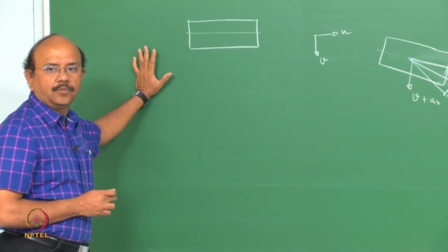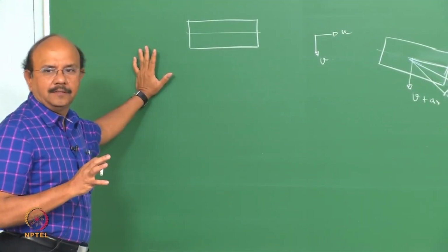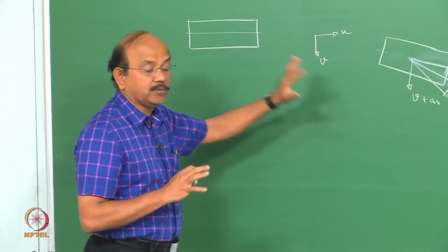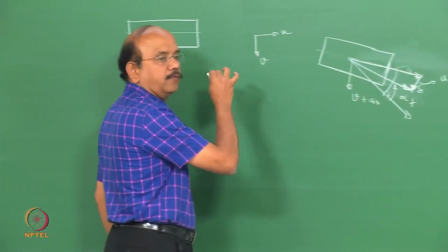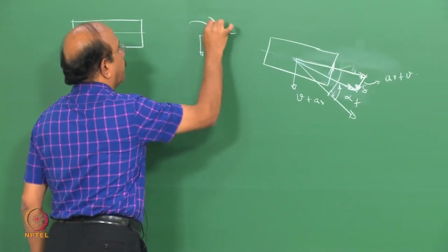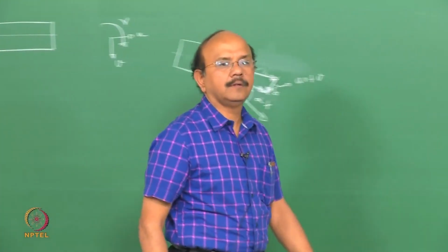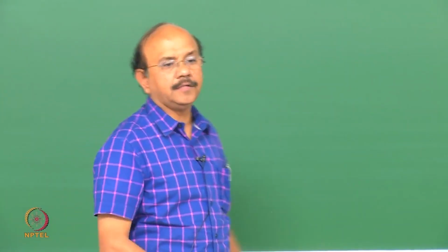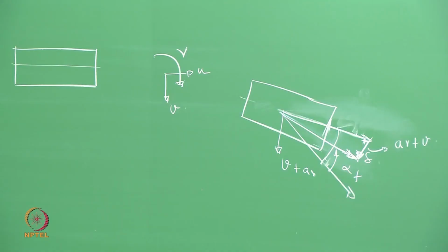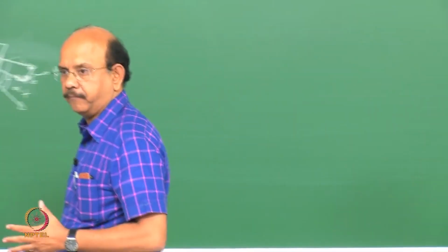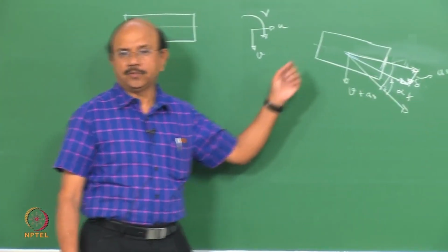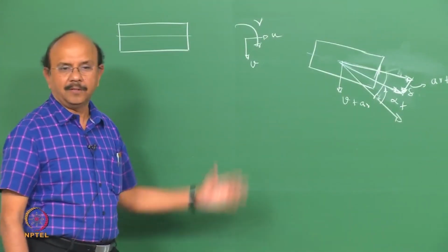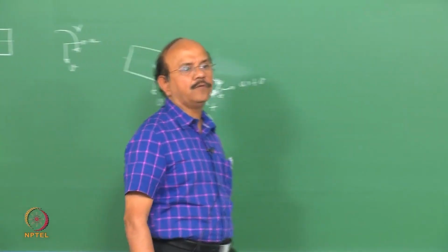Okay? So the equations which I'm going to write down consist of V and R, where R is the yaw rate, right? So we already said that R is going to be the yaw rate, right? We are going to look at a system where U is a constant. In other words, it's a steady state. U is equal to a constant U. We are not going to vary U, and we're going to write down all the equations in terms of V and R.